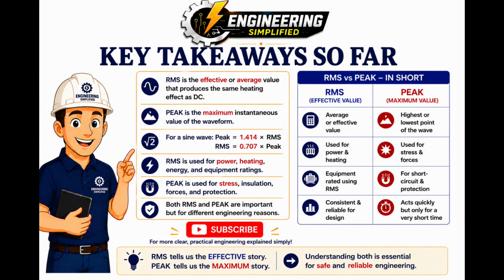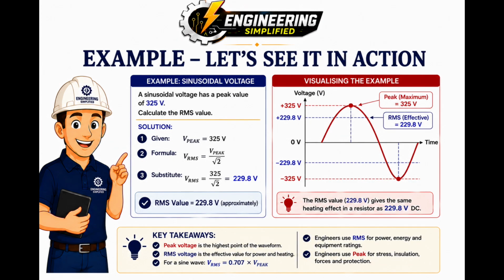Before we move into the calculations, here are the key points so far. RMS is the effective value. Peak is the maximum instantaneous value. For a sine wave, peak equals RMS multiplied by the square root of 2. RMS is commonly associated with power, heating, and equipment ratings, while peak is particularly important when considering maximum electrical and mechanical stresses. Now let's put this into practice.